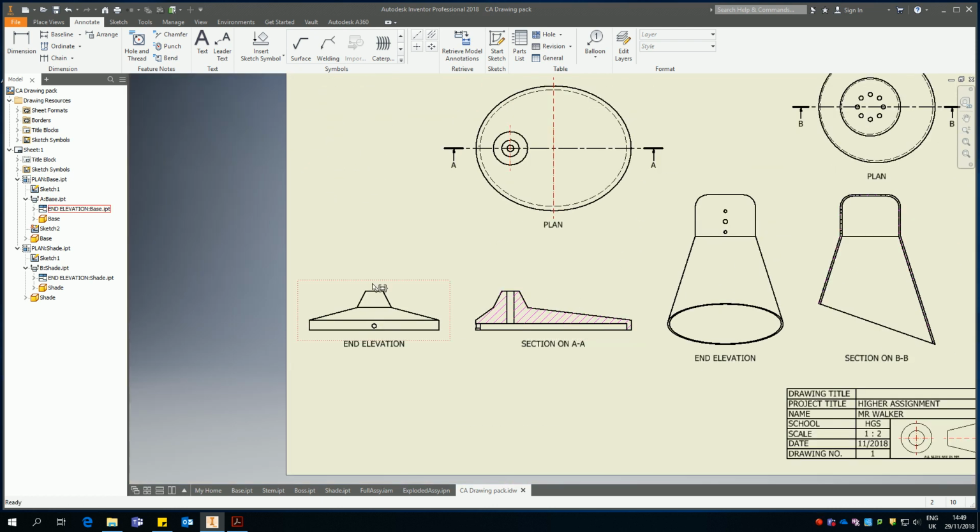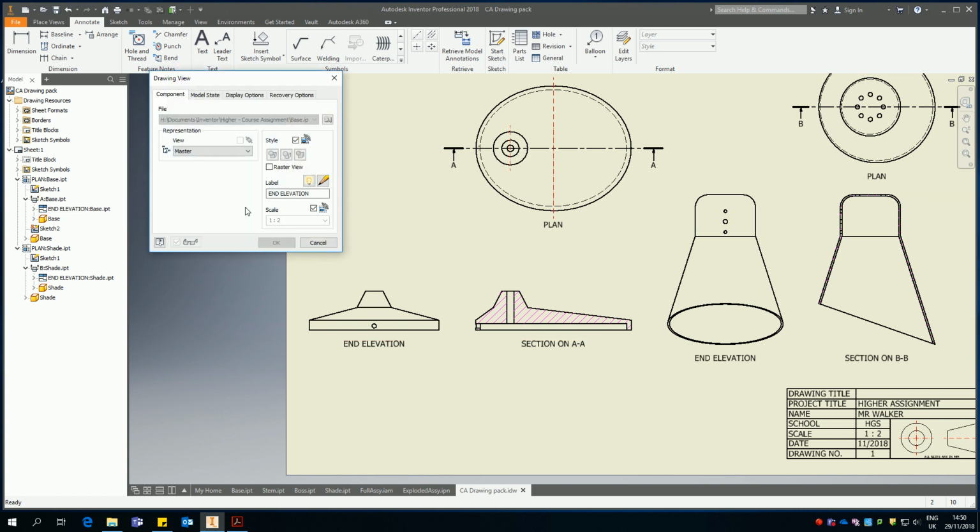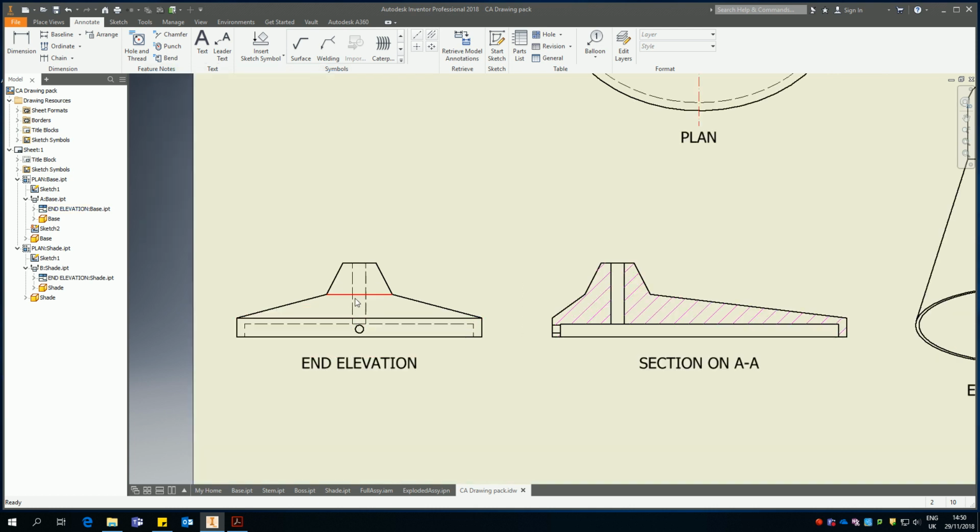On this view here, we've got the central piece, and I've just noticed I'm missing hidden detail. The reason for this is it's a projected view from a section, and while sections don't typically show hidden detail, I'll have to remove the associated nature of it and turn on show hidden detail on this view. Now I should get away with just the normal creation of center lines on here.